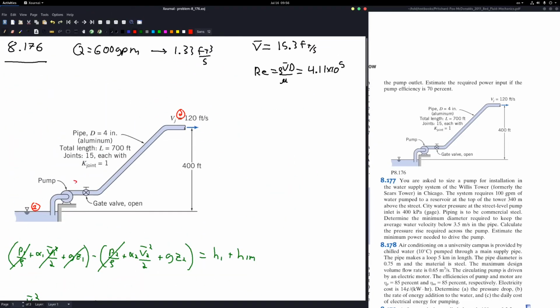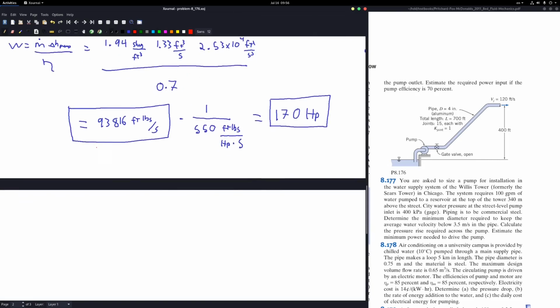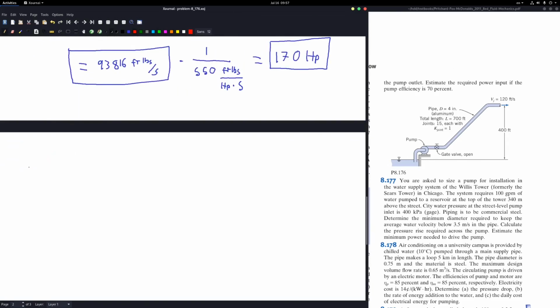Now the other part of the question is also asking for the pressure at the outlet of the pump. So here we will again take Bernoulli's equation, but I will be simplifying a lot of the steps here, so that we just have P3 minus P1. So that means our variation in height we assume is going to be 0. Also our variation in velocity is going to be 0, and we also will assume that we don't have any losses, which is incorrect because we know we have that 90-degree bend, but we'll say that for the sake of simplicity our variation in pressure here is just going to be equal to the power that the pump is outputting.